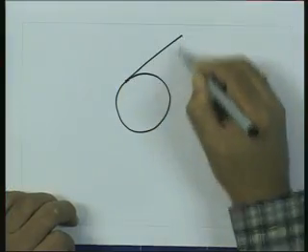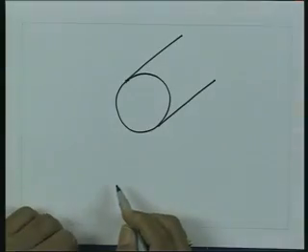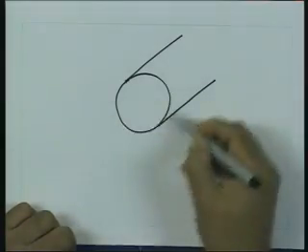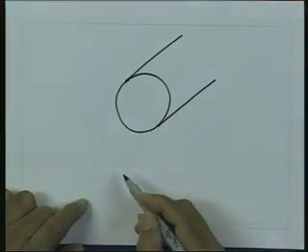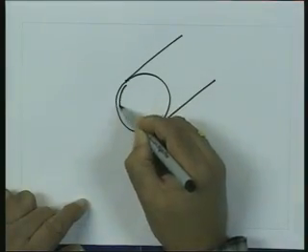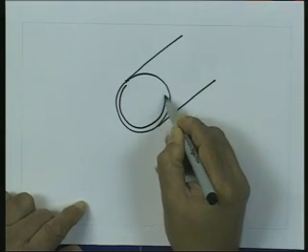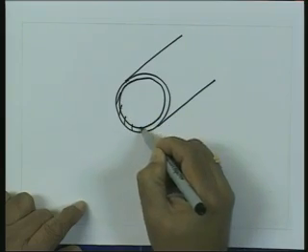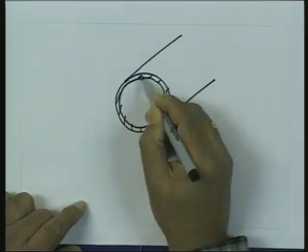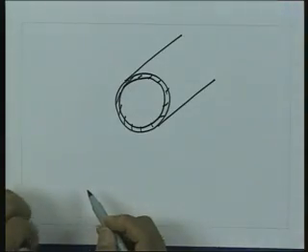So, if I take a conductor, something like that, and the electromagnetic energy is going to propagate along this conductor, the currents which are excited because of these fields are not going to lie in the entire cross section of the conductor. They will essentially be confined to the skin depth of the conductor. Only this is the region where the fields exist, and because of that the currents flow.